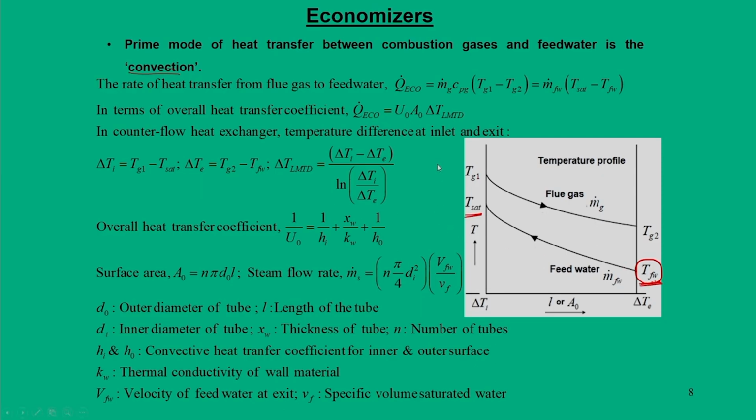For a similar analysis we need to calculate the logarithmic mean temperature difference for a counter flow heat exchanger mode. Then we have to find the heat transfer to the feed water through the energy balance equations. Then you link these equations to the tube geometry through the overall heat transfer coefficient, outer surface area and LMTD.